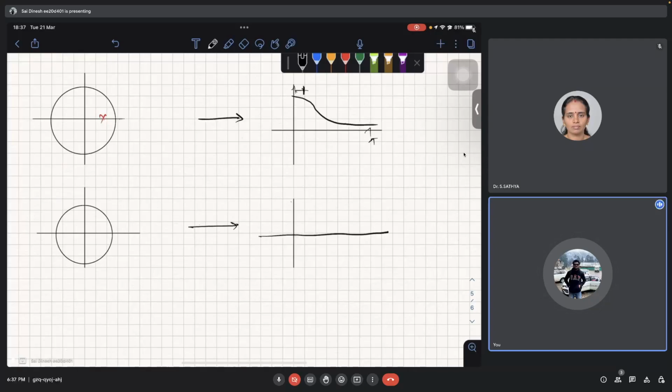But if you only have one zero to place, then we know that the zero creates attenuation. But where do we need the attenuation in a low pass filter? We need attenuation at the high frequencies. So we place the zero at a high frequency. Okay, so now how do we get that? At a high frequency we know that there is a sharp attenuation but then a broader peak. So this will produce something like this, and here we have a broad one.